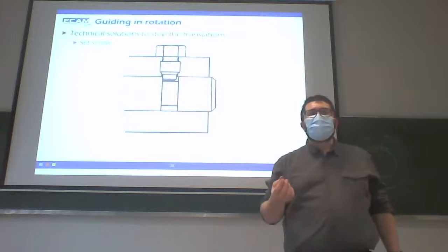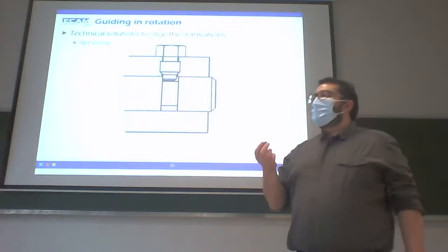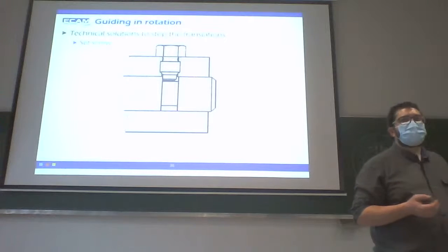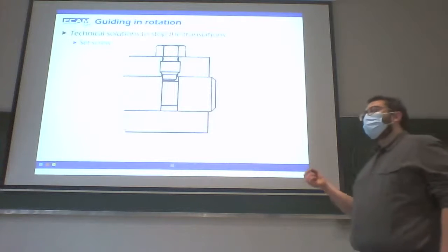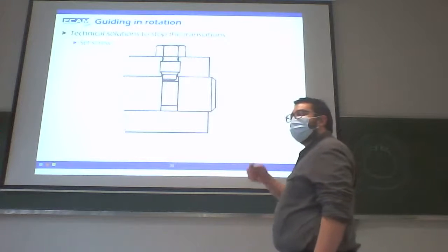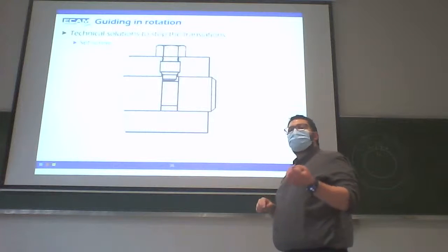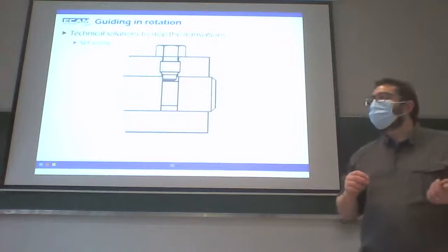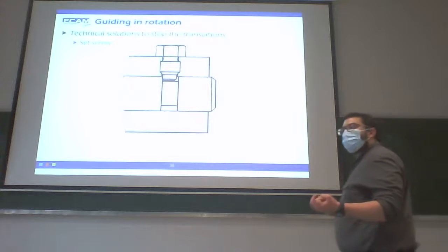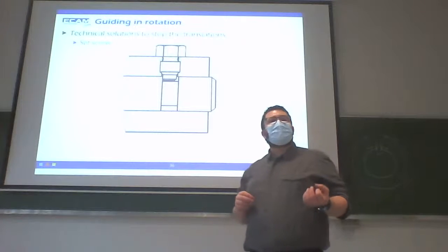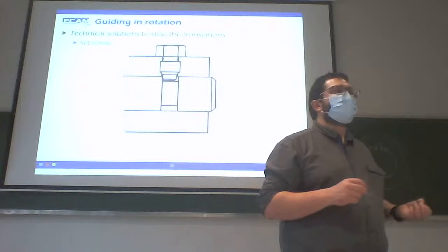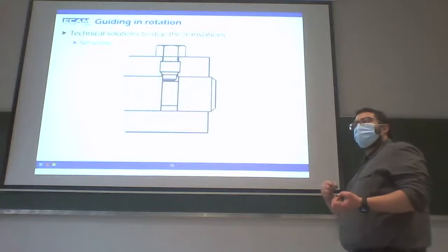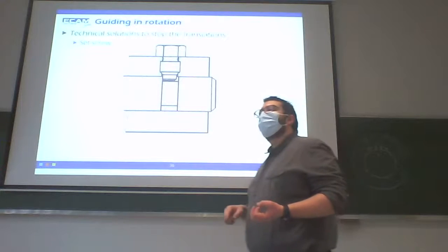When you want to stop the translation of the main screw inside of the main body, inside the main body we have realized a small hole plus the shape of a nut to be able to screw the M3 screw. And inside of the main screw, realized on the manual turning machine of the Fab Lab, we realize a circular groove to put the head of the screw inside it.